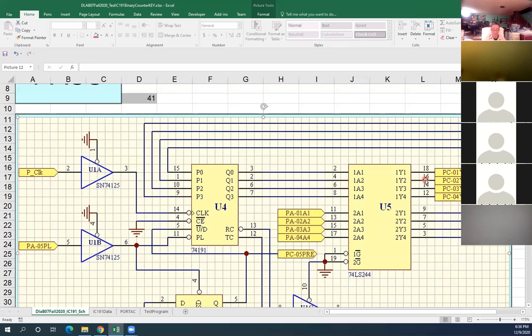Okay, go ahead. First thing, when you fail, they bring it out. Expect data: 1, 0, 1, 0. Right? Now, measure data. Then you see which output failed, which pin. That means they say they read pin number 12 to be 0 instead of 1. It's supposed to be a 1, but you say it's a 0. Yeah, that's what they measure. So you know it failed on pin 12.